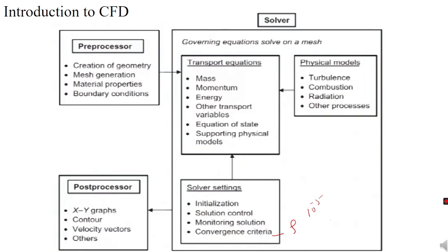So the important thing is geometry quality. It should be clean, watertight. Geometry is a requirement for accurate simulations. Meshing strategy: ensuring mesh refinement in critical areas wherever we need to go for the analysis, especially boundary layers or regions with high flow gradient.